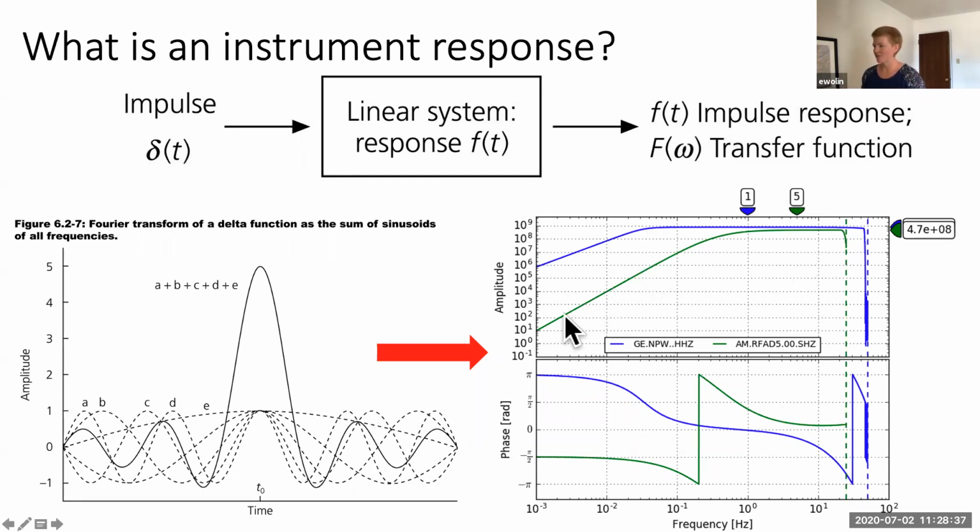And we'll see why that matters when we do the deconvolution. But basically, if you are working where you have a very small amplitude response, when you remove the response, you are multiplying by a very large number, and that can cause things to blow up and your deconvolution to be unstable. So we'll get some hands-on experience with that in the lab.